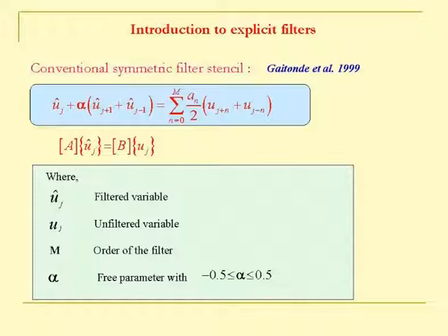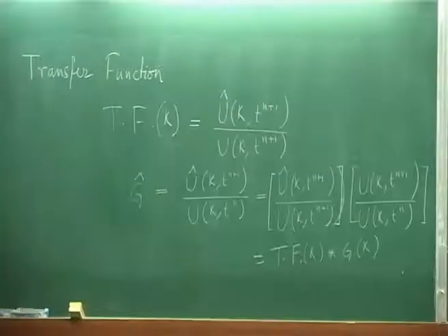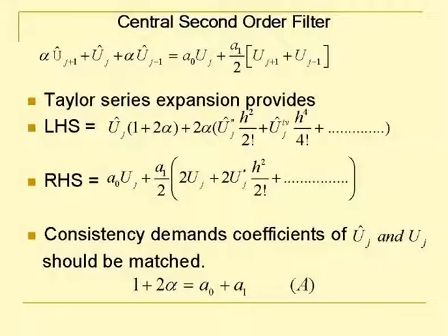So, we have noted that these operations are occurring in the physical plane, and the view that we are taking is in the spectral plane. So, we need to work out how these things are related. You notice that you take the integrated solution to the right hand side and make these operations in sequence. You start with A0, then you have A1, A2, and so on, all the way up to A of capital M, and capital M was defined as the order of the filter.